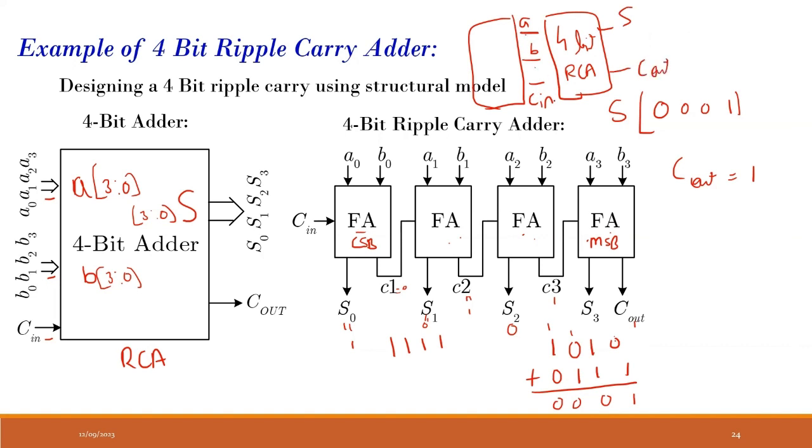Carry in, in the sense like in microprocessors, if there is an overflow? Yes, the same concept. Microprocessors, FPGAs, they are all digital circuits, so they'll also have the same issue of carry. So this carry might be the overflow bit of the previous block? Yes, exactly. And this carry out is the overflow of this ripple carry adder. Okay, sir, thank you.